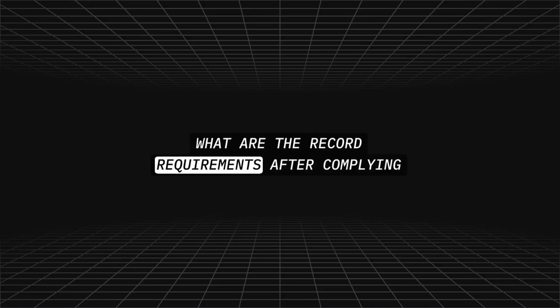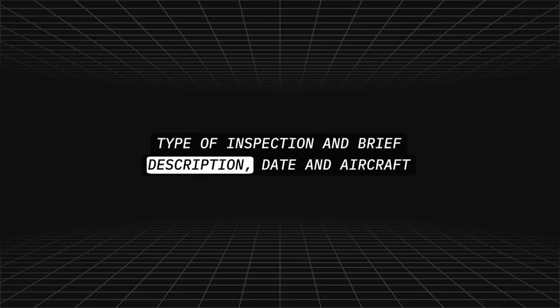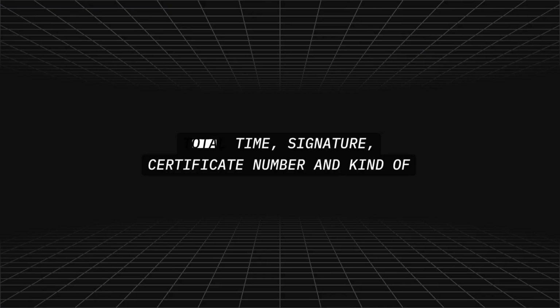What are the record requirements after complying with a 100-hour inspection? Type of inspection and brief description, date and aircraft total time, signature, certificate number, and kind of certificate, and an I certify statement.